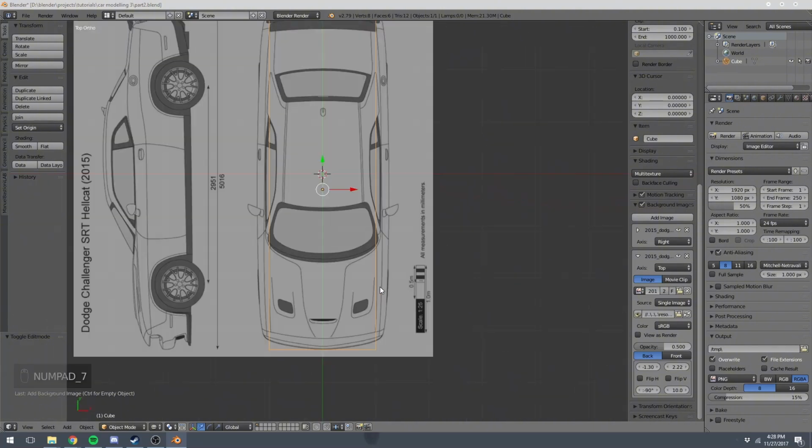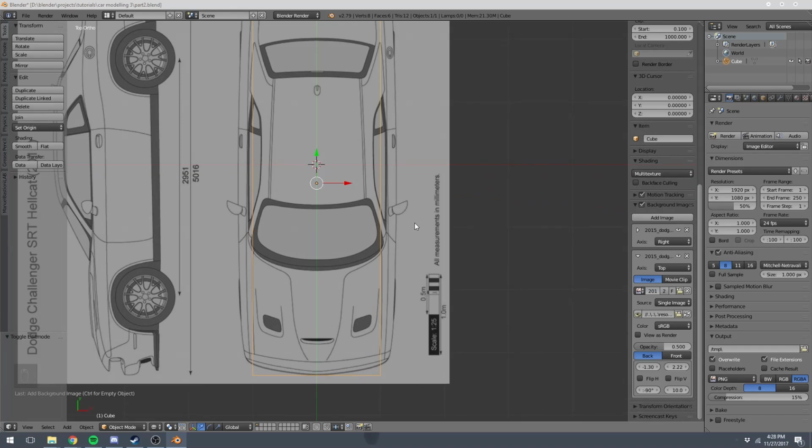So I'm going to go ahead and stay in our top view actually, and scale our object, which is S. Right now we're changing the entire size of the thing, but we just want to change the width, and since width corresponds to our x-axis, we can click scale. Oh, and just so you know, if you right click while performing an action such as scale, it just cancels it. So to set the width for the car, we're going to scale and click X to lock to that axis. And just scale it to the width of the car.